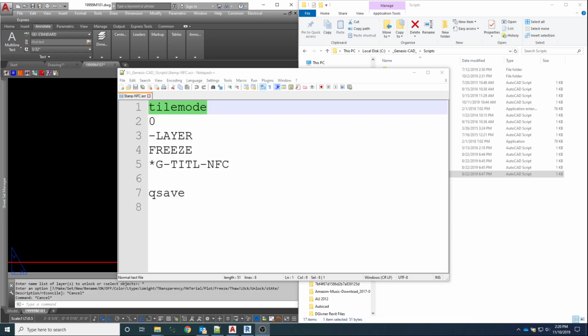The purpose of this video is to discuss scripting in the AutoCAD environment. Scripting is a collection of commands that you type into the command line at the bottom of your AutoCAD. All it really is, is a text file: anything that you would have typed, in the order that you would have typed it. The enters, the changes of lines within it, are the actual enters you would have typed inside of AutoCAD.